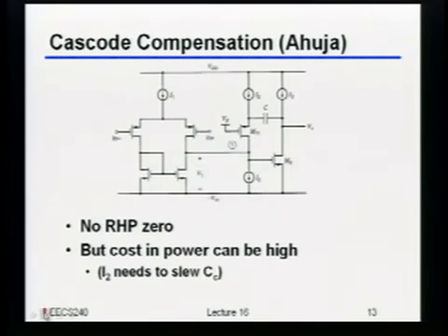So the way to do that is actually conceptually pretty easy. So imagine that I just have my two stages, and then I have my Miller capacitance on the second stage. Well, guess what? If I just put like a little amplifier there, and actually I'll flip the ordering just so that it will be more clear how I've done it. Imagine I just put a little amplifier right there. Okay? So that amplifier obviously likes to look at this input and drive that output. So again, conceptually, this should make it so that to the extent that this amplifier is a good amplifier, I should only be taking signals from this output over here and feeding them back, but not going the other direction, right?